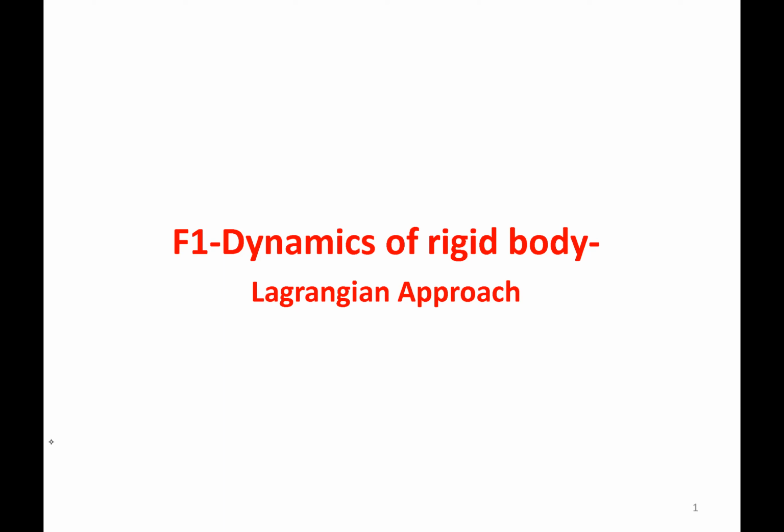Before starting the lecture of today, I would like to say that I added some slides on the shoulder singularity. There is also a video that shows what happens. You can click on the link. We can discriminate the boundary singularity from the shoulder singularity by the fact that in both cases there is a loss of influence of the joint motion on the end effector motion. But in the boundary case, we always have a solution for inverse kinematics.